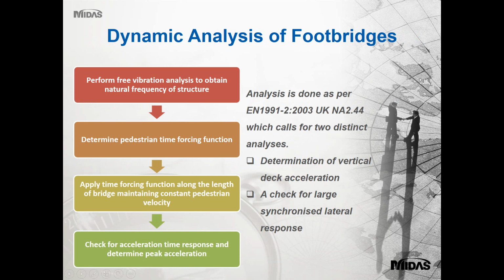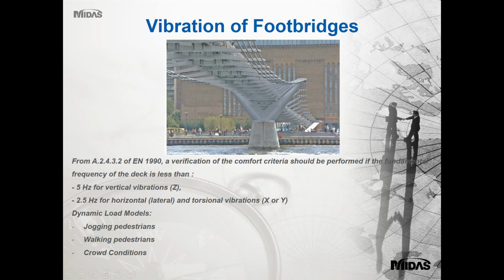Similar to the dynamic analysis of heavy rail loads, we also have dynamic analysis of footbridges. Now this is more of a serviceability check where we are focused on the peak acceleration of the footbridge under human induced vibrations. It's an interesting method of analysis where we first check the natural vibration of the footbridge, and if it's within a particular value of frequency like shown here, we run the analysis in a more detailed manner for dynamic loads.